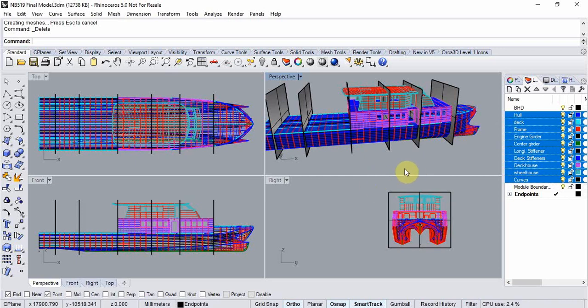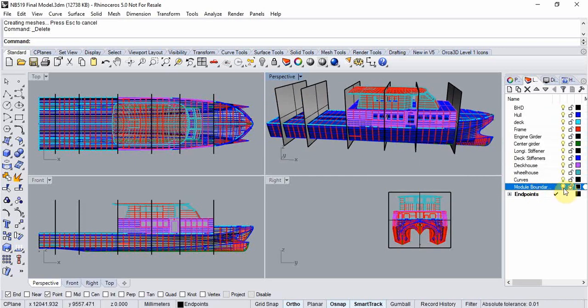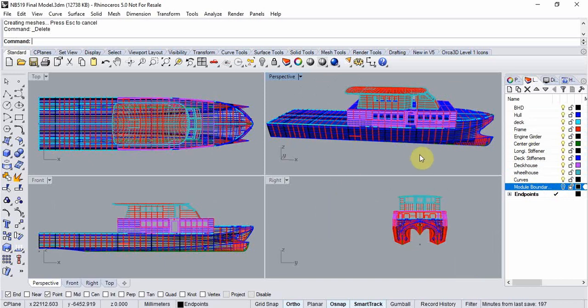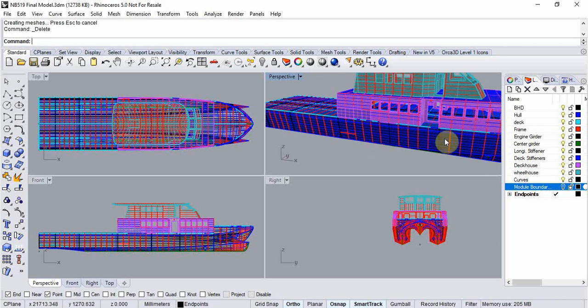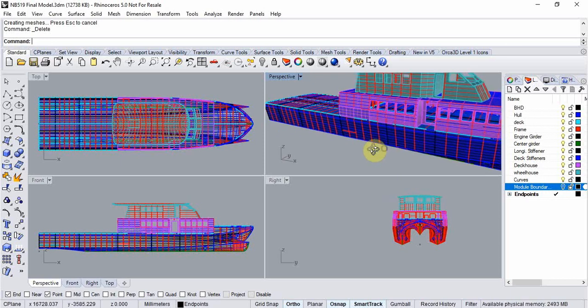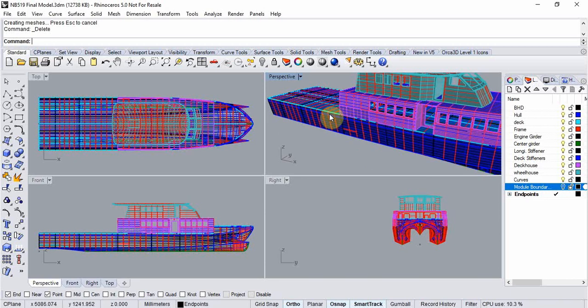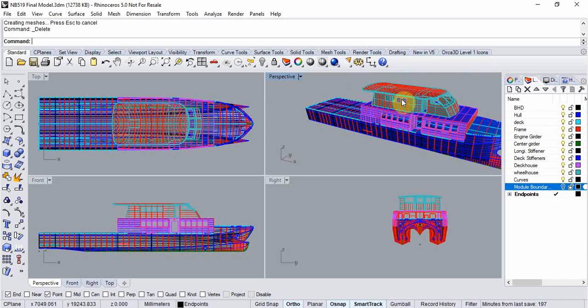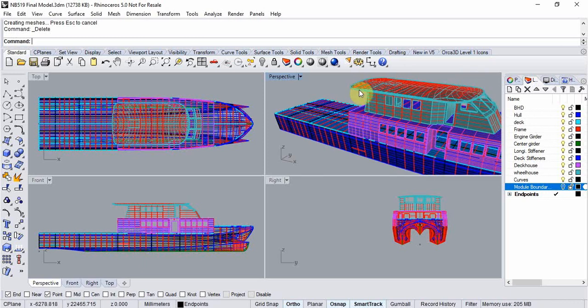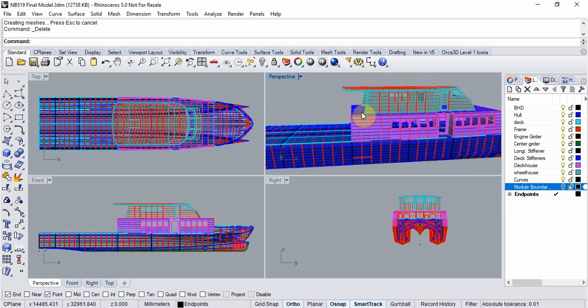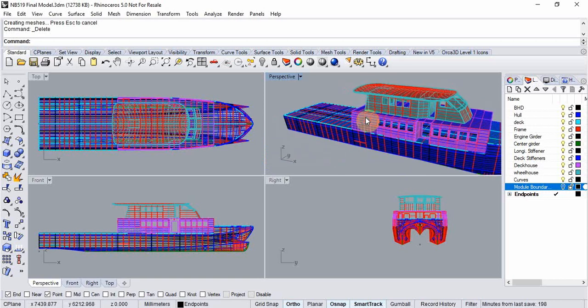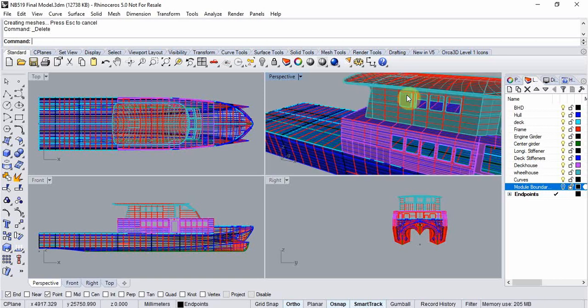The procedure that we're going to use to build the deck house will basically be as follows. First, we'll want to extract all the curves from the geometry to create Maestro endpoints. This will basically consist of all of the stiffener traces on the hull and the superstructure, as well as any feature curves on the hull and superstructure, such as the deck edge, the chines, any longitudinal knuckles in the house, the edges of the top of the deck house, and the curves defining the cutouts for the windows and doors, and say the aft end of this fascia plate, so that we could create meshes to model some of these features.